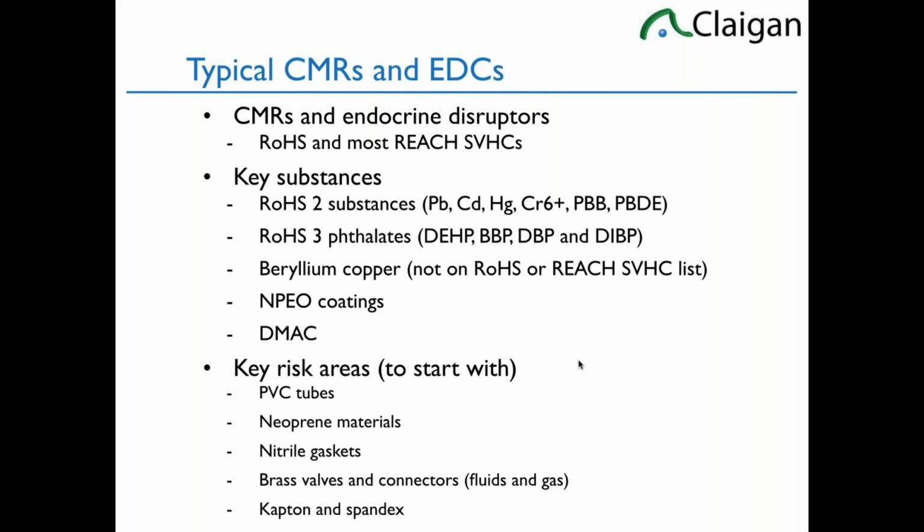PVC tubes very commonly use the phthalate groups, the low molecular weight, DEHP, etc. They can be made with other ones, adipates, terephthalates, TOTM, which still has residual DEHP, but well below 1,000 ppm. So those tubes, unless you design specifically otherwise, are very commonly using DEHP, but you can buy them, or design them nowadays, using alternative materials like adipates or terephthalates. The phthalates above are really orthophthalates. So substances people always call phthalates are really orthophthalates. The terephthalates, which are very similar, do not have the reproductive toxicity or endocrine disrupting capability of the orthophthalates, for one reason or another.